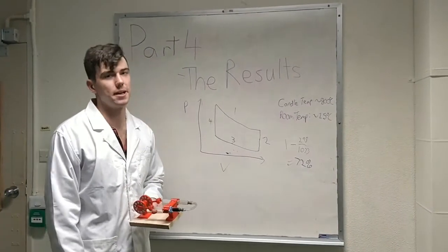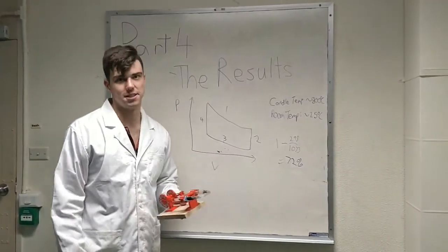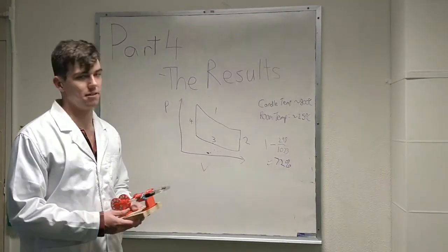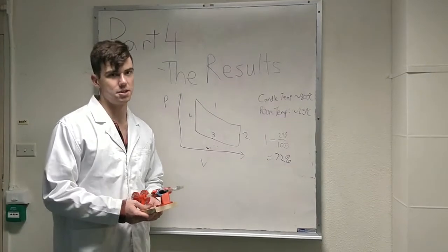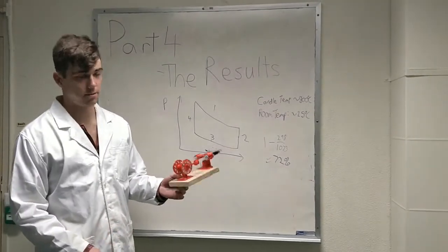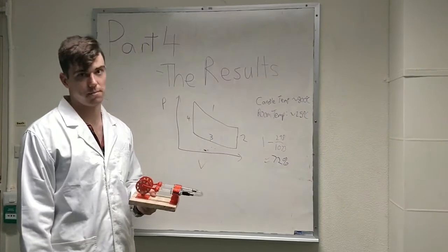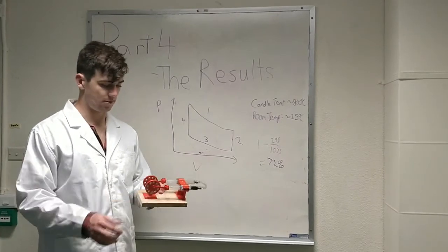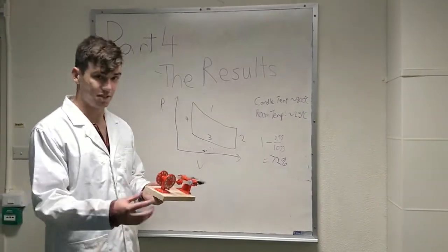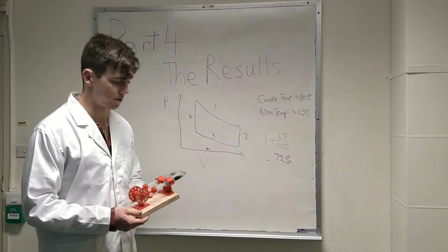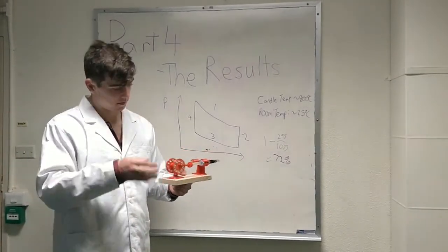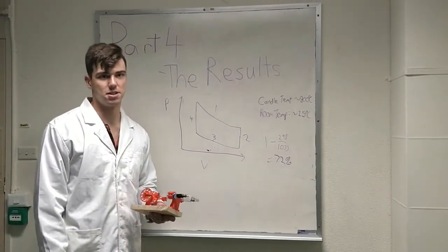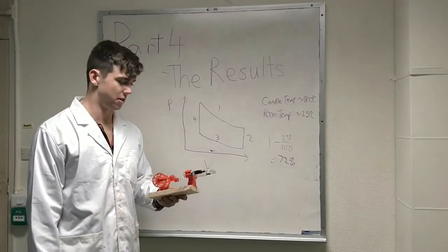Ultimately, if I was to build this Stirling engine again, I would make some modifications to the design. I'd use larger syringes, which would allow a greater amount of potential energy stored as heat in each syringe. I would also use one centralised flywheel, as the two flywheels being slightly offset I believe was a cause of the friction. I'd also have a tighter fitting between the arm and the edge of the syringe, as I feel like that was rattling, which indicates a loss of energy as well. Despite this, I feel like the engine was a moderate success, as it did manage to kick back, showing that there was some semblance of the Stirling cycle, even though it did not perpetuate its motion.